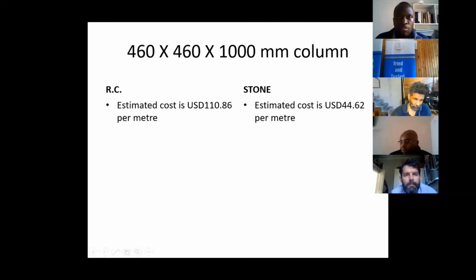For the entire structure, it would now be getting into detail if you're going to look at the location of the building, as well as the number of stories, and the hiring of a crane would also be considerable if you are to have a very tall, high-rise building. But from here, we can establish that there is a significant reason to investigate further the cost effectiveness of stone as compared to concrete. So when you look at the costs and also the environmental comparison, you get the picture that there are benefits not just from sustainability, but also from cost effectiveness.